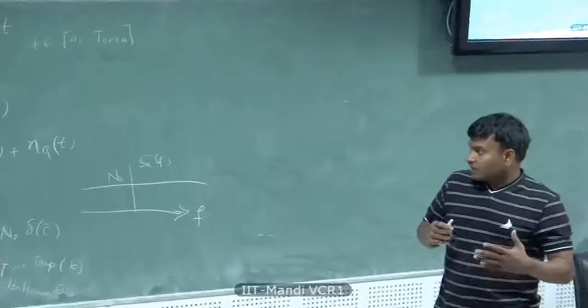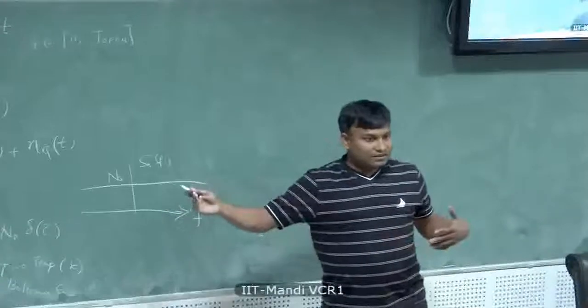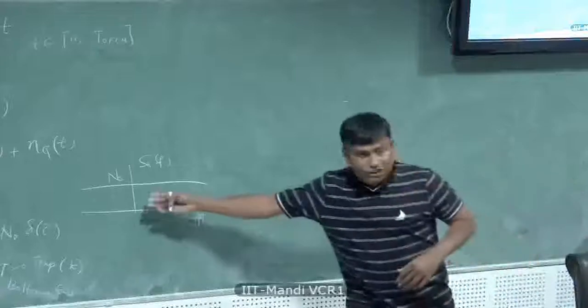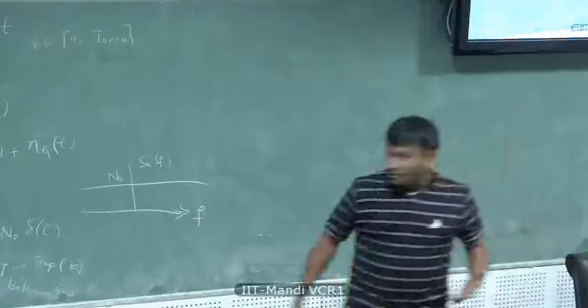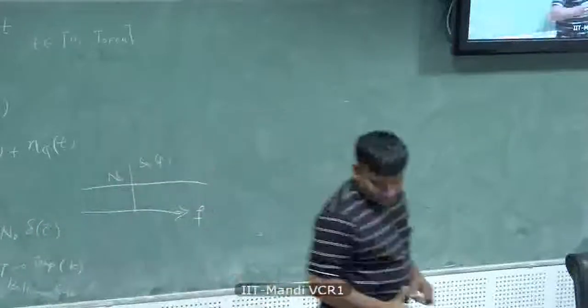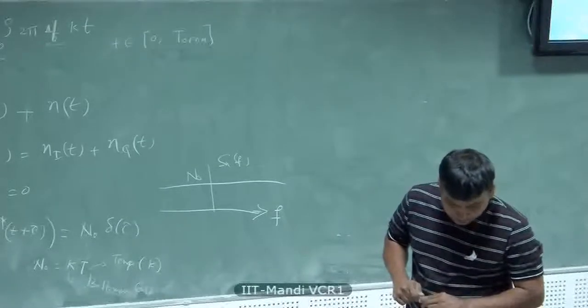Don't mix up or confuse white and Gaussian. White and Gaussian are different. They imply different things. White talks about the spectral content. Gaussianity talks about the probability density function of this random variable n. They're different concepts. Okay, so that's enough about modeling the noise.